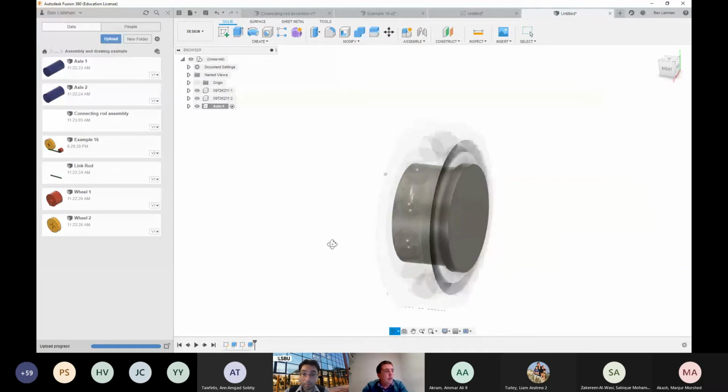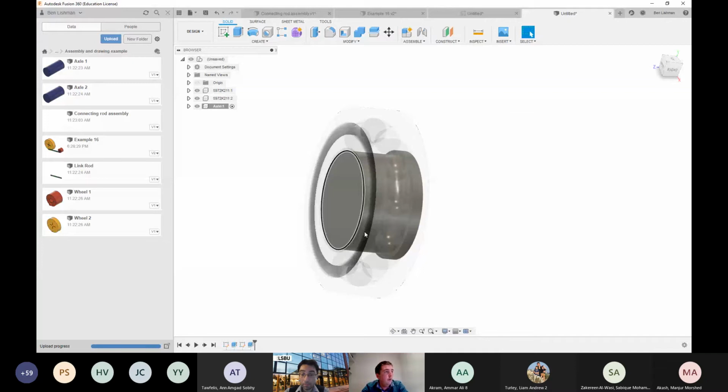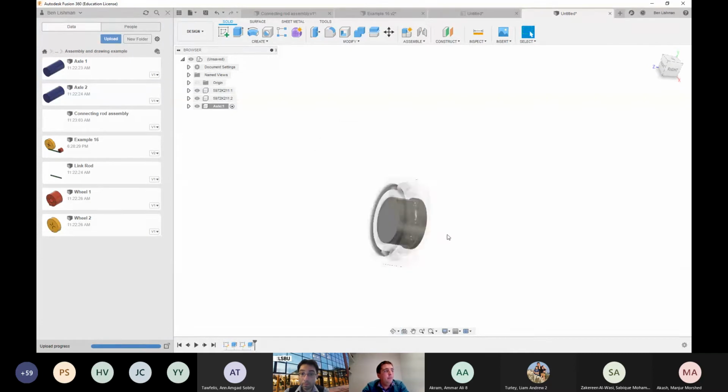And the important thing now is that my bearing has something that it can rest against on the axle. The bearing can't slide backwards, it can only slide forwards on the axle, for example. So if it's a very tight fit, I can keep on hammering the bearing forward until it sits on that lip on the axle. OK, that's now the axle that I want.